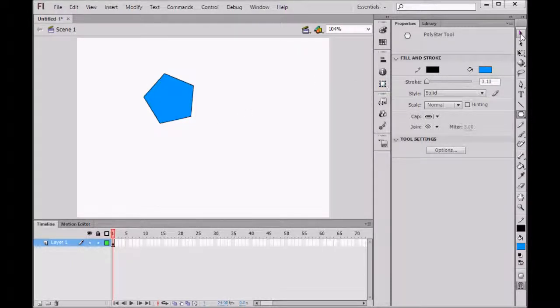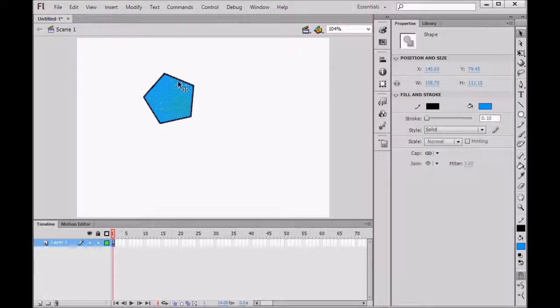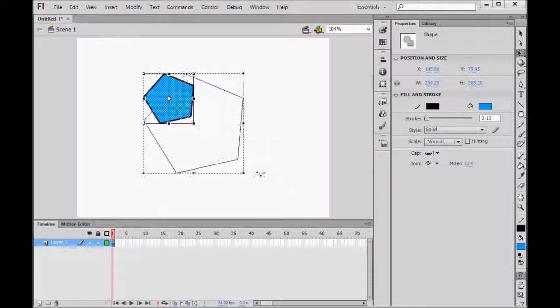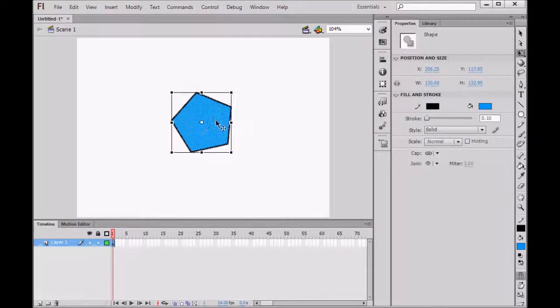and now I'm going to show how to rotate things. So with the object selected that we just drew, by double clicking or drawing a box around it, choose the third tool from the top. This is the free transform tool. This will allow us to shrink or grow our object, and once again, if we were to hold shift while we were shrinking and growing, it would grow in perfect proportions. Okay, so that's how you can adjust the size,